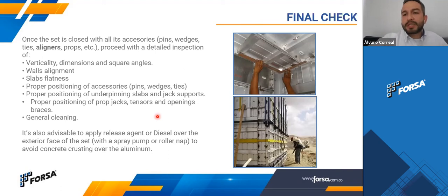So this guy and his crew must check the verticality, the walls alignment, that the slab is level, the accessories are properly positioned and in enough amount, that underpinning slabs and everything is put in the right place. And general cleaning, as you can see here, these sets are very clean, and this is the way they're supposed to look every day.